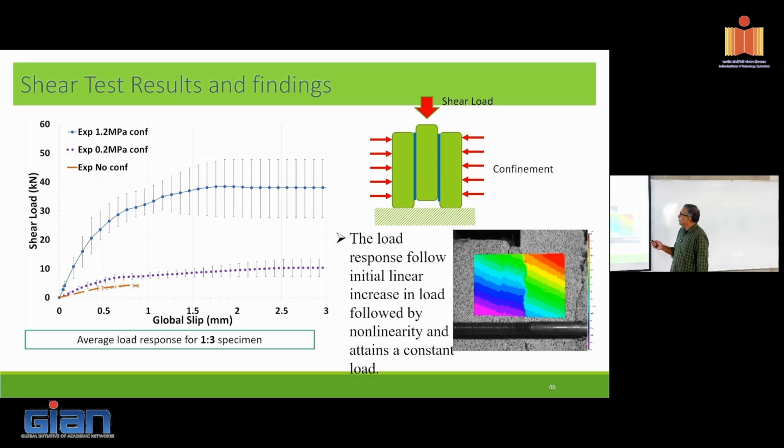But just to explain to you, if I have two blocks of masonry, these could be three filaments in fact. Printed filament 1, 2, and 3, and this could be the interface that forms between them. It's exactly the same mechanics. So if I understand the behavior of masonry, where we've done masonry tests looking at shear transfer at different levels of compression, now I can come up with constitutive theories.